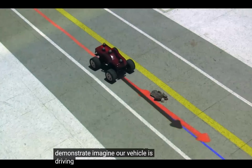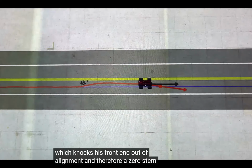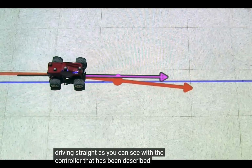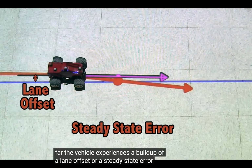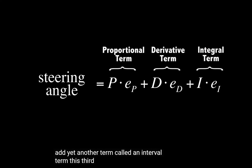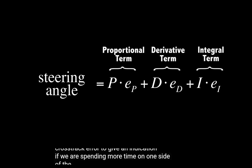Imagine our vehicle is driving along and hits a pile of rocks, which knocks its front end out of alignment, and therefore a 0 steering command no longer keeps the vehicle driving straight. As you can see, with the controller that has been described so far, the vehicle experiences a buildup of a lane offset, or a steady-state error. One way to address this problem is to add yet another term called an integral term. This third measurement sums up the cross-track error to give an indication if we are spending more time on one side of the trajectory or the other.